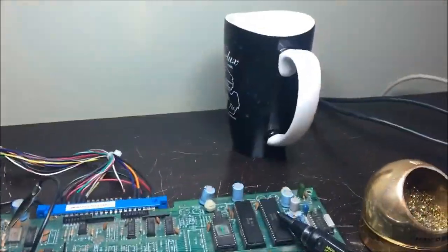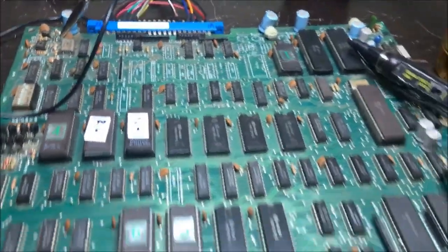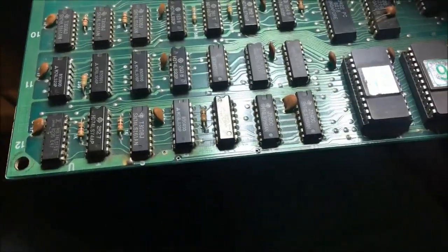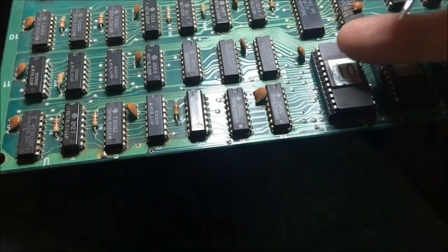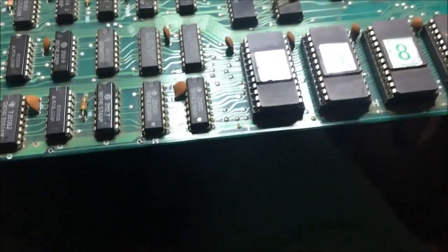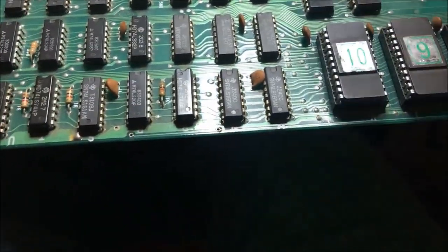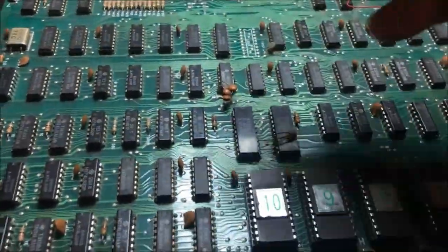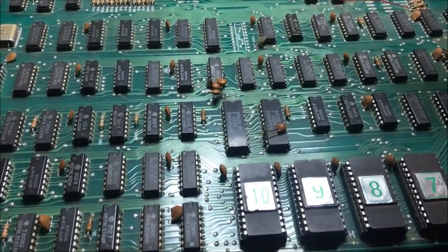Okay, I have started doing some probing around on the board, and since I have no video, I was just probing some of the select lines on the ROMs. These are basically all graphics ROMs. These are tiles, and these are sprites, I believe. I'm not really sure, to be honest with you. I know I can look at the Qbert schematic, but just preliminarily I'm probing around for signals, control signals.